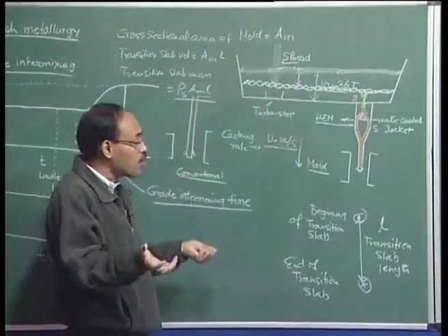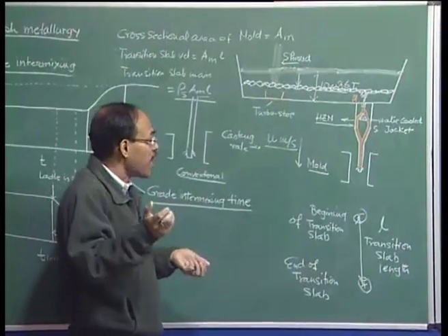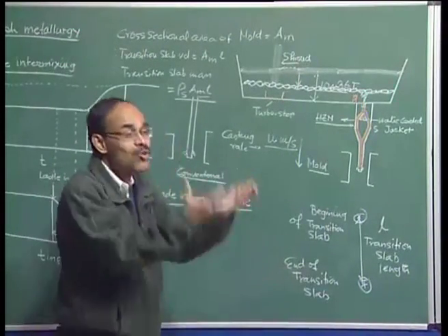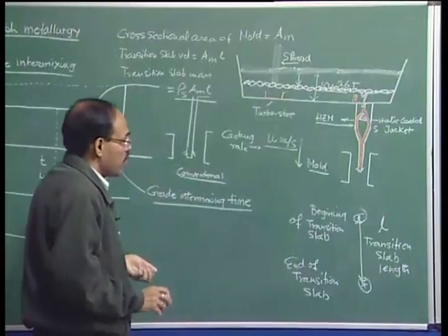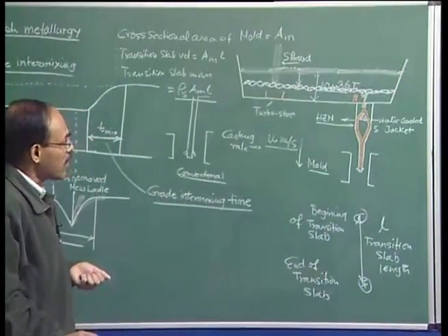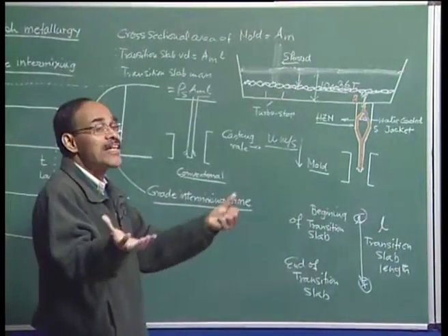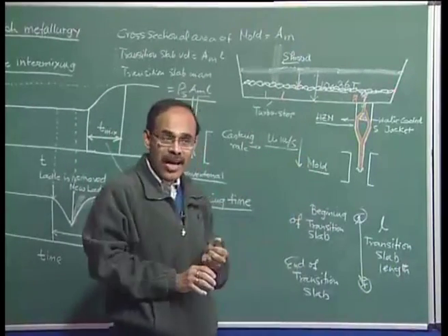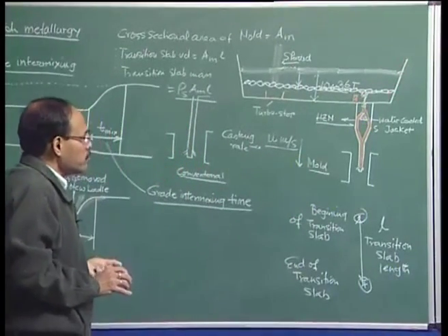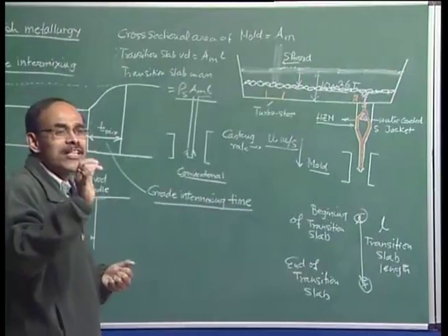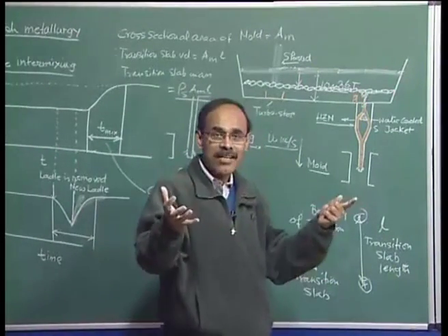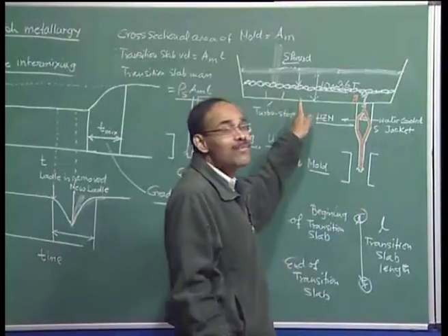So, the tundish is now broken, and the refractory is to be relined. The skull is going to be salvaged by physically breaking apart the refractory lining of the tundish, and the skull is then going to be recharged back into the electric arc furnace. Every plant very meticulously weighs that skull, because they want to find out what the yield from the tundish is.